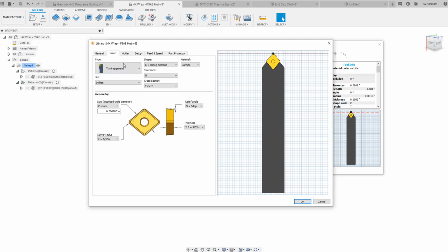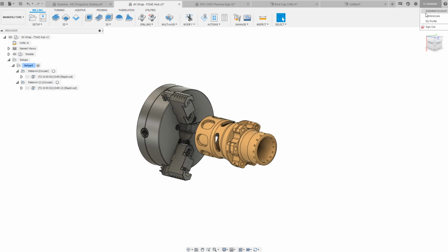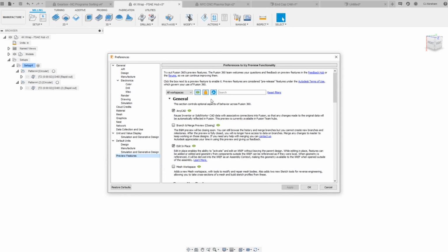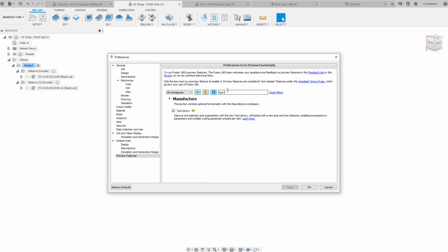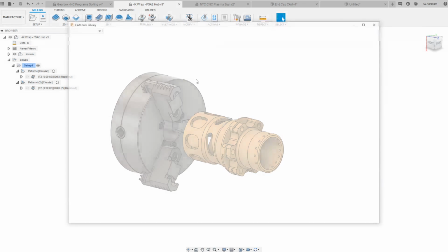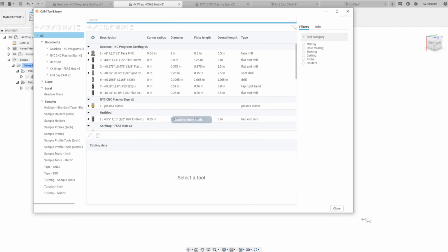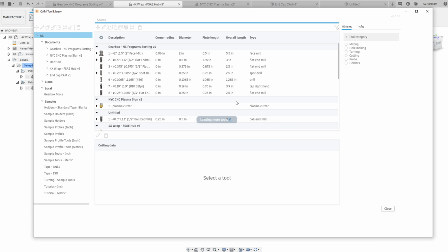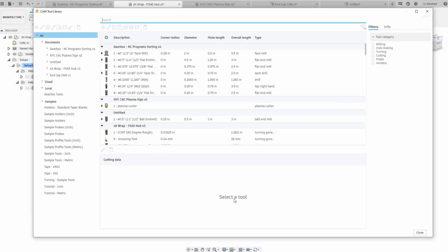Okay. So I was told that they're asking for a CNMG insert. Yeah, let's do the new tool library. So if you want to use the new tool library that's still in preview, if you go to preview features and search for tool library, you'll get this checkbox for the tool library preview, which I'm personally quite excited about. And now when you click on the tool library, you get this awesome new interface. And the most obvious change is to the cutting data panel here. So now we have multiple feeds and speeds per tool, which is something that's been really well received.